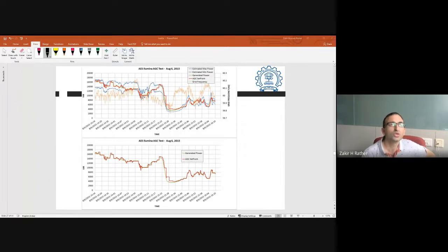So what you could think practically is that there is a concept of the ancillary service market, which those who are working in power systems should be familiar with. If inertia is being procured in the ancillary service market, then you have a market to go and participate in, and potentially earn revenue. And if it does make economic sense to keep a margin for that, you will operate it at non-MPP. If it does not make economic sense, you will not operate your solar PV plant, or particularly the solar PV system we are talking about here, at anything other than the MPP point.